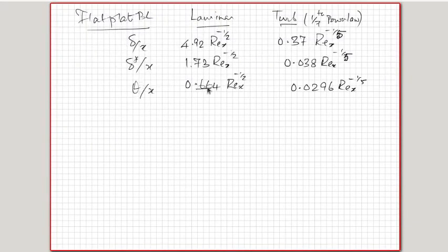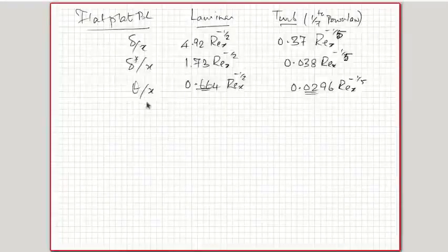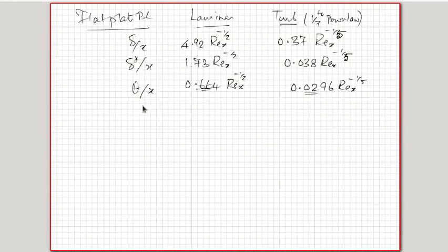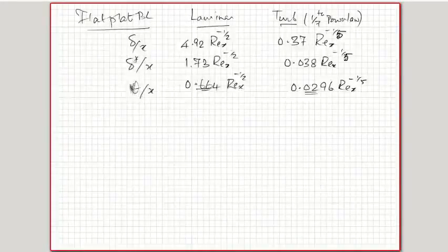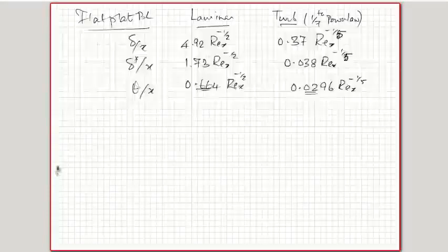You can see that these have the same constants as in the case of Cf by 2 for the flat plate boundary layer. That is because of the relationship of theta to Cf by 2 in the momentum integral equation. So that is one point I wanted to convey regarding the definitions of different kinds of thicknesses. You can see that delta star and theta do not involve that 99% business, but are actually an integral all the way up to the free stream.